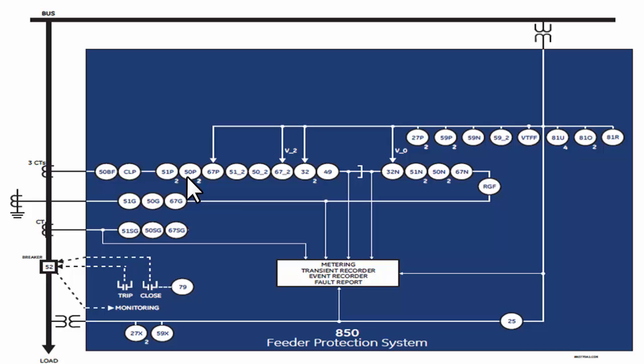and directional overcurrent, negative sequence overcurrent, negative sequence instantaneous overcurrent, negative sequence directional power, and the cable thermal.